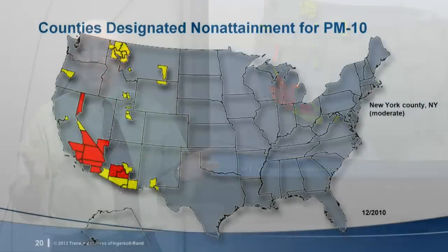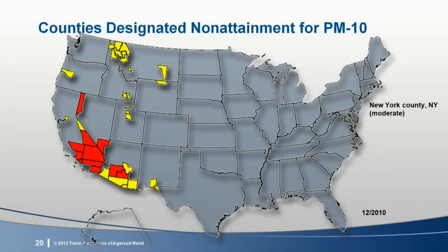Here's the latest EPA map for PM10 non-attainment areas. At least MERV6 filters are required for buildings in all shaded locations shown in both yellow and red. This shouldn't be a big problem since the air handler probably has a cooling coil with a wet surface, and Section 5 already requires a MERV6 filter upstream of any wet surface device.